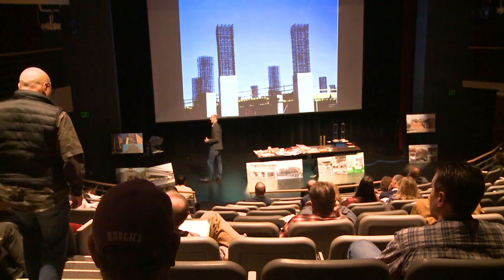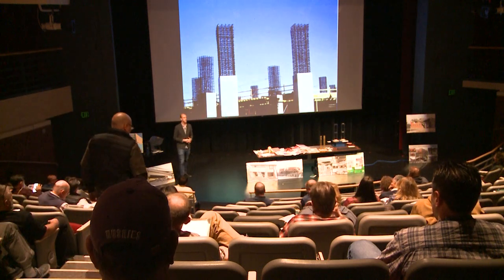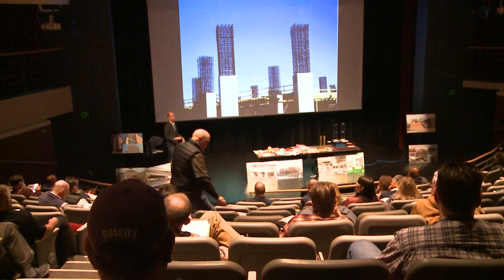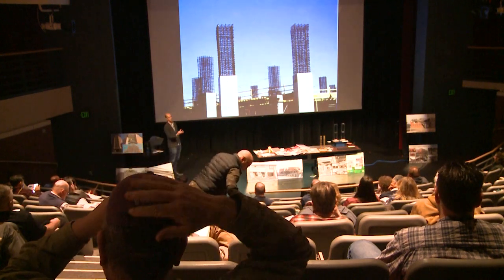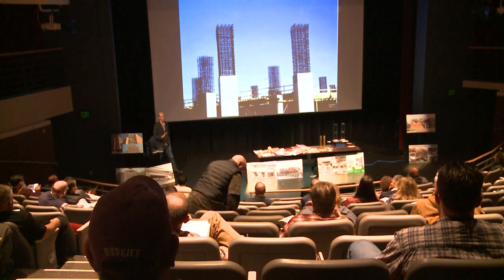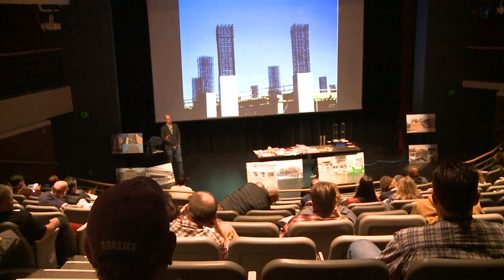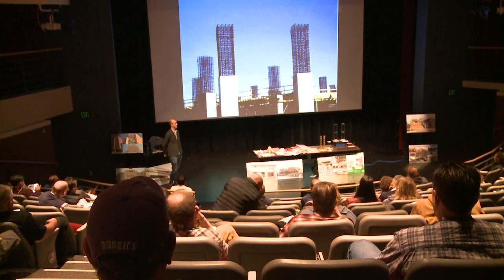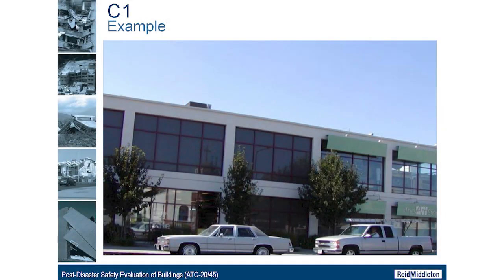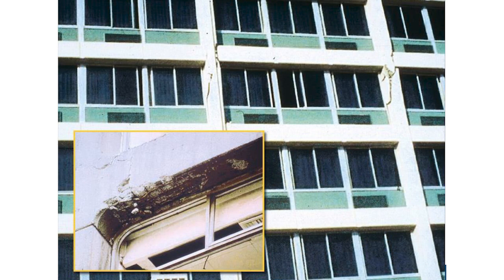So, really the effectiveness for reinforced concrete to be resilient, to be ductile, and to deform without breaking like a paper clip, and not like our piece of chalk, is dependent on that detailing, despite as much grief as our contractors may give us for making them do so. So here are some examples of concrete columns. Here's some damage. I think that's the same example Rami showed earlier with the damage to the beam column joint, and also some major shear cracking through the concrete column.